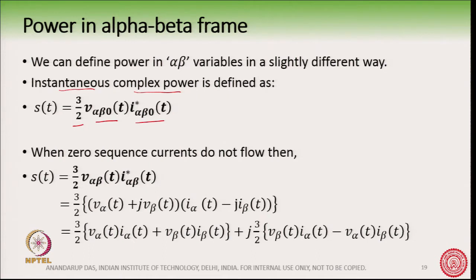So, we put the V here, and for an inductive load the current is lagging, and so we put I star here, so that these projections are positive for an inductive load. So, the Q is positive for the inductive load, and Q is negative for the capacitive load. That is why we use the star concept.